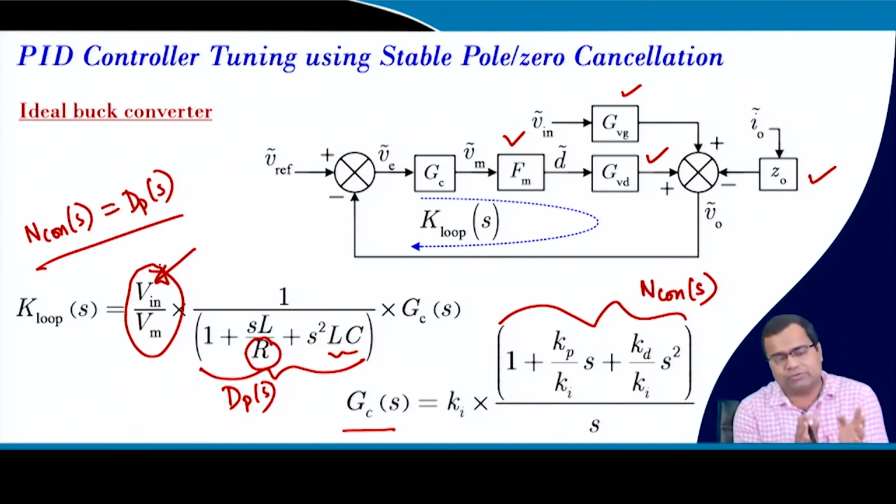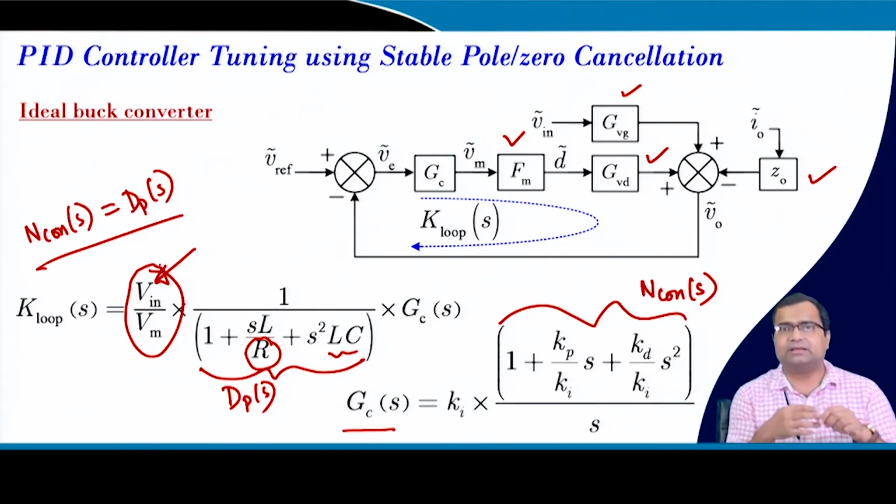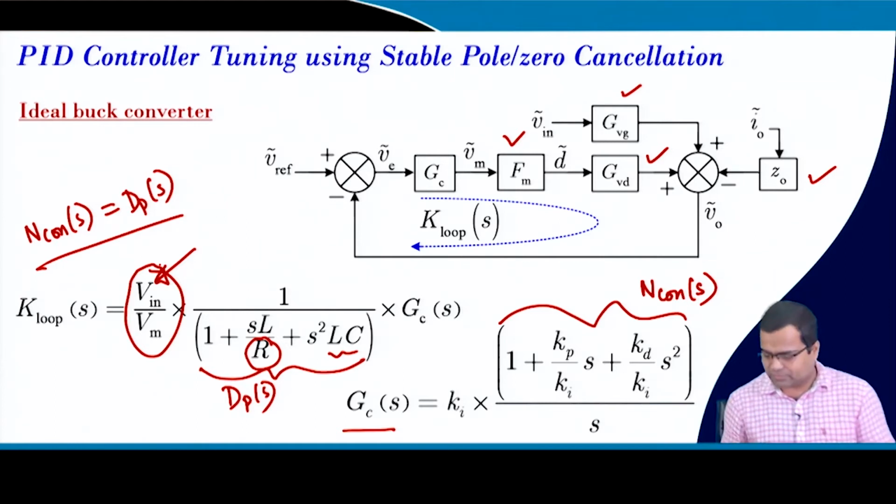Okay. So, by using an input voltage feed forward, because we saw in lecture number 14 as well as, I think, lecture number 17, where we discussed the feed forward control along with the feedback, we can achieve input voltage insensitivity, like an input voltage invariance, in the loop gain by means of feed forward.